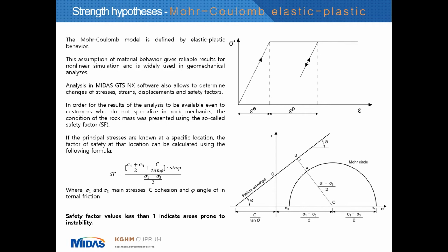Another element of the numerical modeling is the selection of an appropriate strength hypothesis. In the analyzed case, we applied the elastic-plastic model using the Mohr-Coulomb strength hypothesis. Generally speaking, in the static load system, this strength criterion allows for a good reflection of the actual situation within the rock mass. We verified this many times with the use of underground measurements in in situ conditions, and our research proved that the Mohr-Coulomb criterion fits our deposit very well in static conditions.